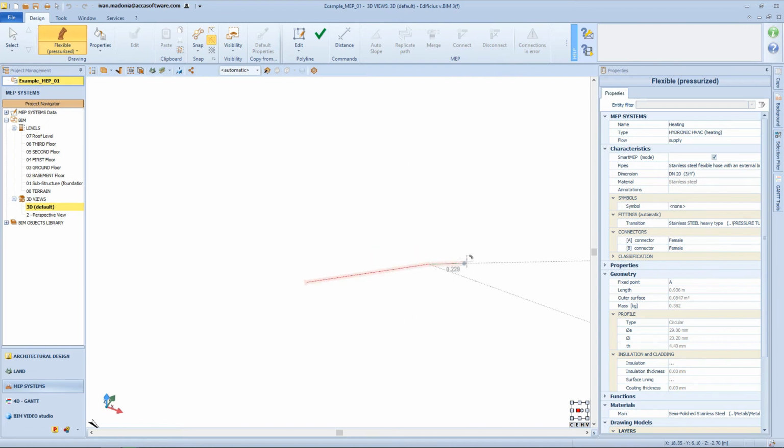Once the first section has been defined, you can finish drawing the hose by clicking on the button represented by a green flag in the top bar of the drawing menu or right-clicking and choosing the finish item. Alternatively, you can trace successive sections of the hose, possibly using the protractor, which reappears as in the initial entry, and typing the length of each section from the keyboard, or positioning the endpoint of the section graphically in 3D.